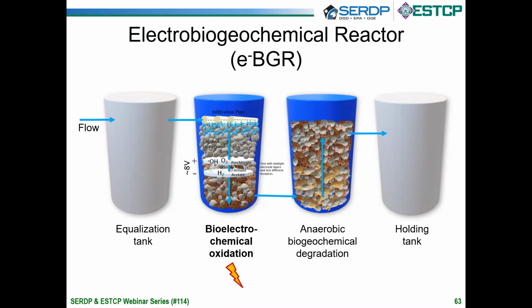So this is where the electrodes sit, and we had done initial tests with the groundwater at different potentials to find the optimum current. And for this specific site groundwater, we settled on 8 volts. And then this reactor is backfilled just with gravel, basically, to help the gases escape. So what's not shown here is the gas management, but you do have to help the oxygen and the hydrogen to get out, or in the case of oxygen, also to become dissolved.